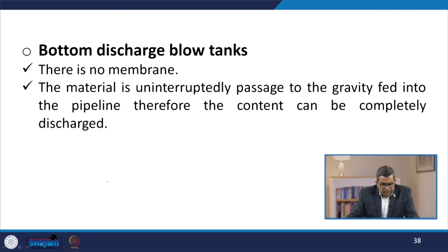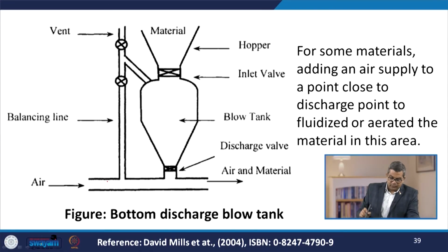Let us talk about the bottom discharge blow tanks. Now here there is no membrane. The material passes uninterrupted, gravity fed into the pipeline. Therefore, the content can completely be discharged.